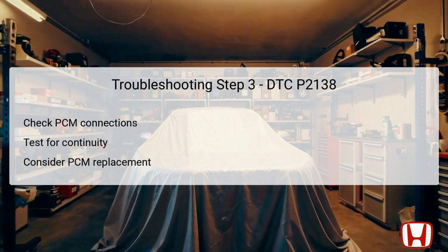After waiting a minute, the technician disconnects the PCM connector A51P to test for continuity between specified test points. These test points include PCM connector A number 45 and number 38. Continuity between these points is critical for verifying that the PCM is functioning correctly. If continuity is present, the issue could stem from other system components, while a lack of continuity suggests the need to check the PCM further or replace it if authorized service information suggests so.